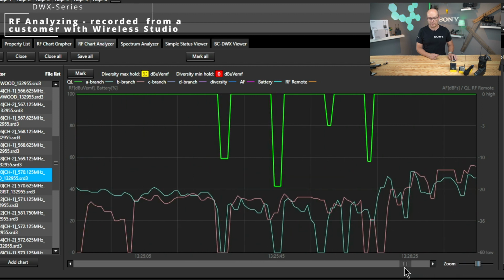If we zoom in a little bit, here you see one antenna is going down to 20, the other antenna is going to 0. Not enough signal noise ratio. So the phase change, we're using QPSK as a modulation in the Sony system. The phase change cannot be detected because the signal noise ratio is not good enough. That's the same for any information, even in an audio signal.